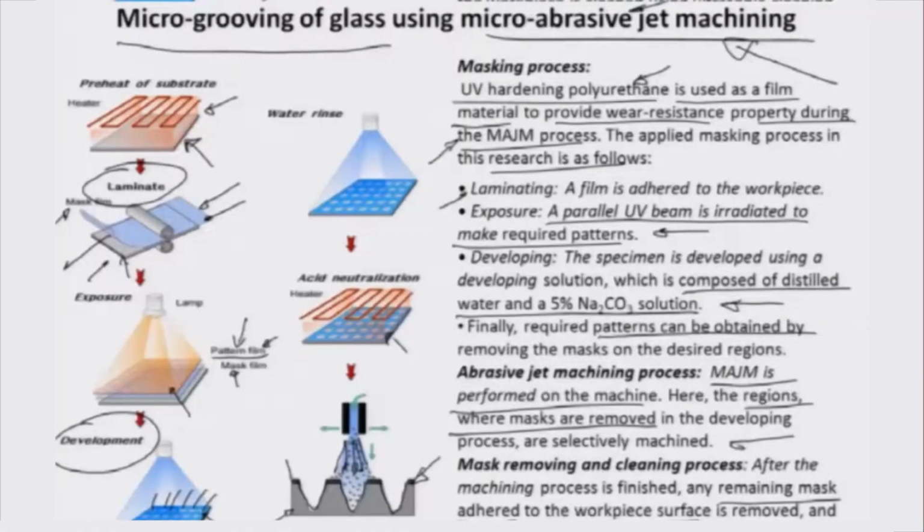One of the ways to clean it is by using ultrasonic machining or an ultrasonic bath, where ultrasonic frequencies are used on a water bath to create enough kinetic energy, so that anything like an impurity on a surface, and maybe a layer of the surface, is taken off. This layer on the surface is probably the one which adheres onto the mask. So as soon as this layer is eliminated, it releases the mask. At places where there is a remnant of the mask, as you can see here, these black regions are further processed using ultrasonic cleaning techniques.